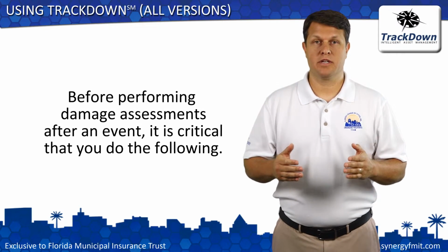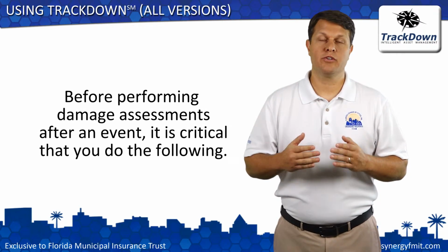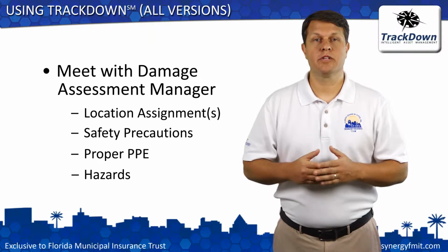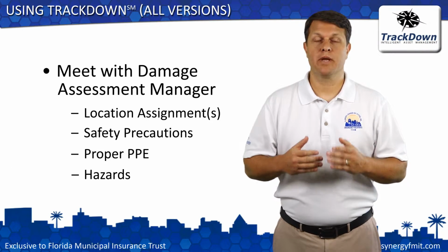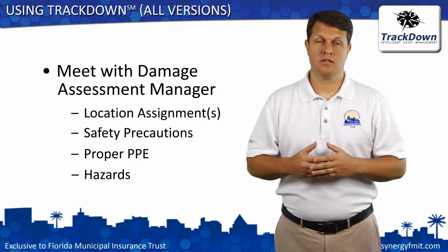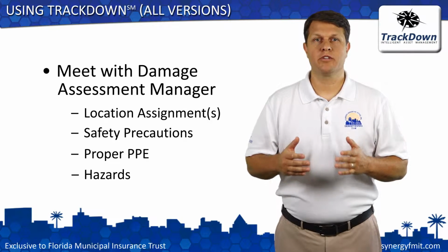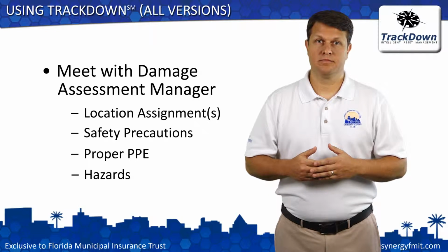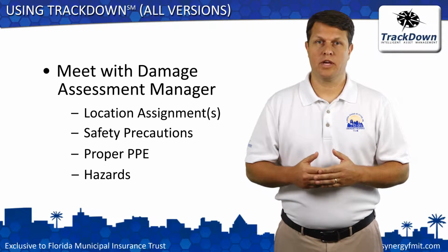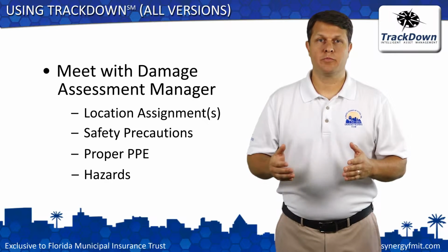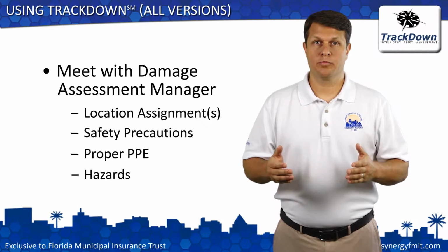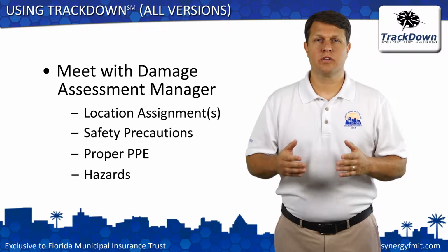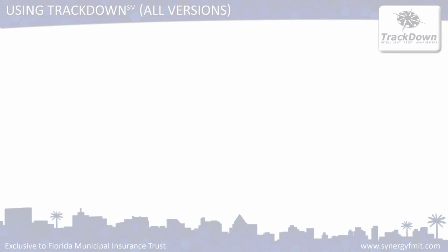Before performing damage assessments after an event, it is critical that you do the following. First, meet with personnel at your municipality that are responsible for managing the damage assessment process. This will allow you to receive the information you need to perform the assessment safely and effectively. This information will include what locations you are assessing, safety precautions to take, personal protective equipment to wear, hazards that may be encountered, and other critical issues of which you should be aware.